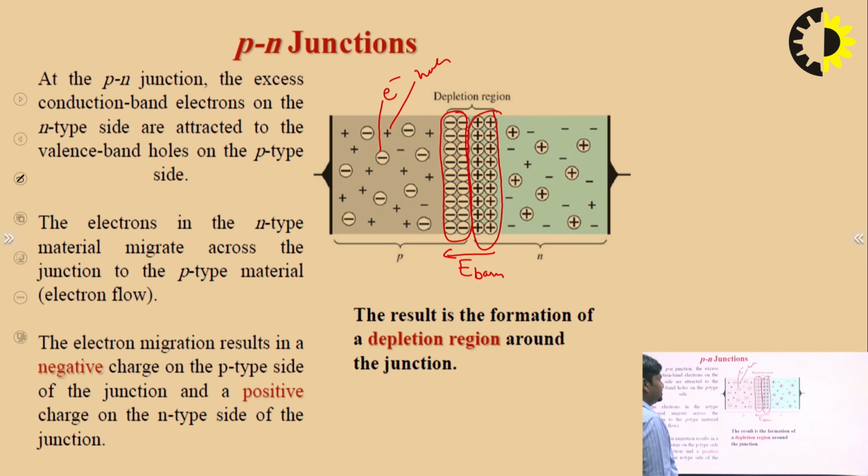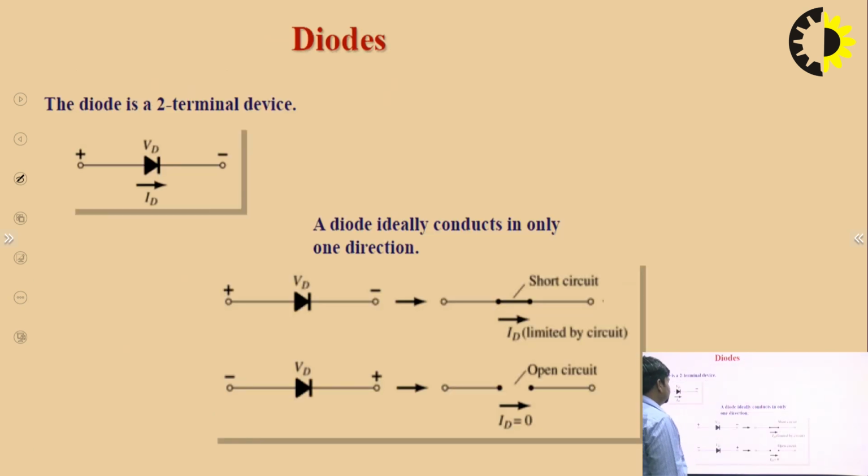So, the PN junction diode works in forward bias and reverse bias conditions. This is the symbol of the PN junction diode, and this arrow denotes the diode current. This side is P and this side is N, and the direction of current in the diode is from P to N. In forward biasing, P is connected to the positive terminal and N is connected to the negative terminal.